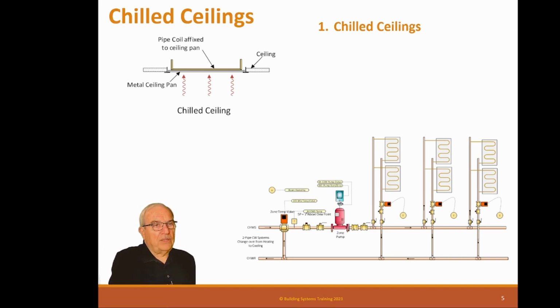And we've had people come up and try to open the ceiling by raising a tile, and that doesn't work very well. These have flex hoses on them, but they'll only flex 4, 5, 6 inches. You can't take a tile and move it way out of the way unless you prepare for that. So we've had people damage systems by fighting a tile, trying to get it out of the space, and they actually break a hose, which is not a good thing in a chilled water system.